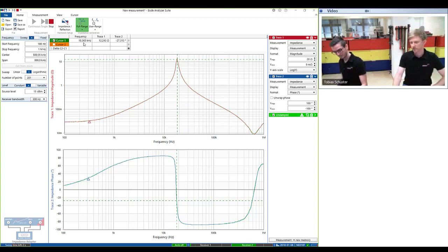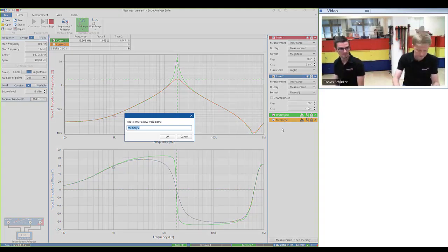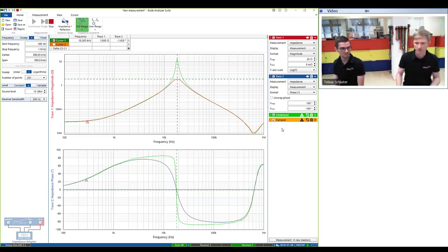And now we're gonna damp the filter using an RC damping network, where you can see the resonance is now lowered by roughly a decade, so it's only 2 ohms then, or 1.8 ohms left. So that's the damped filter. You can see that the frequency response of the filter does not change too much, actually only at resonance it is influenced. And this damping network is a 44 microfarad capacitor with a 2 ohm series resistor.